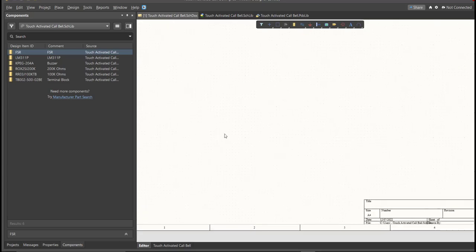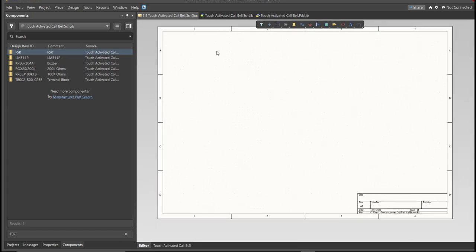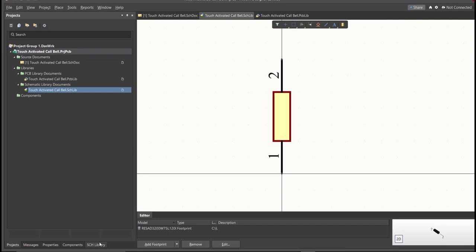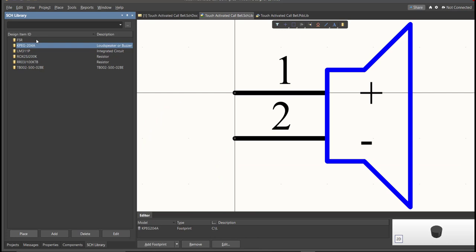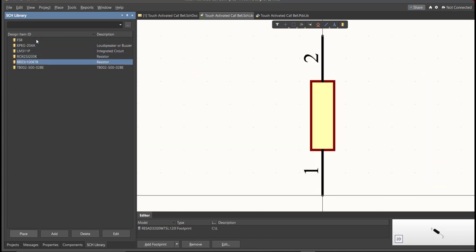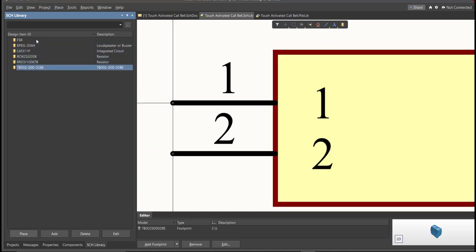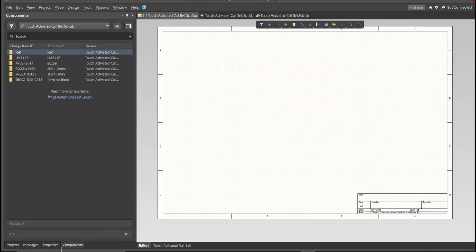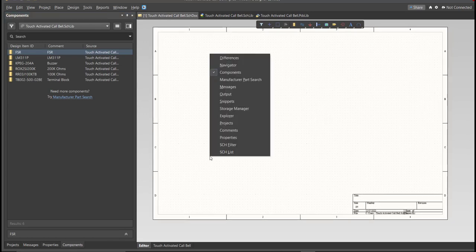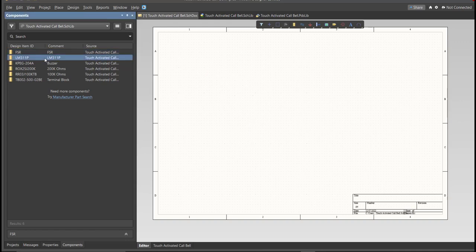After you finish all the components in the BOM list using a library loader, you can check here in Schematic Library panel all the added libraries. So these are the added libraries for this PCB. Next, we're going to put all of these in our schematic doc. So go back to the schematic doc and click on Components. If there is no component in your panel, just press K in your keyboard, then click on Components. Now you can see here the library for this project. So we're just gonna drag the library inside the schematic sheet.